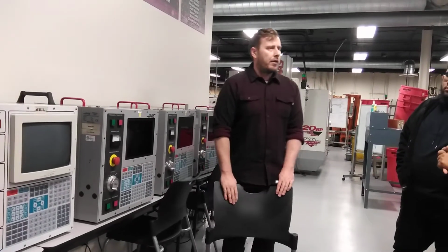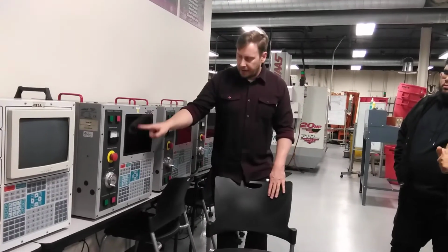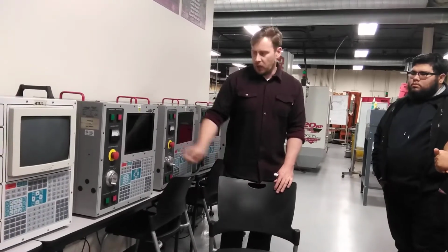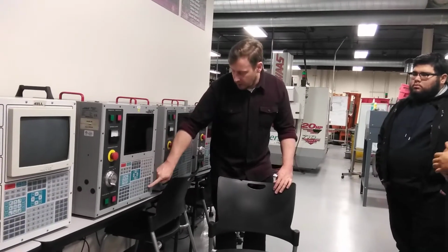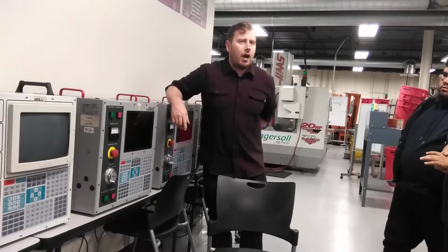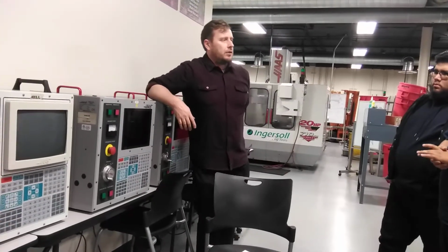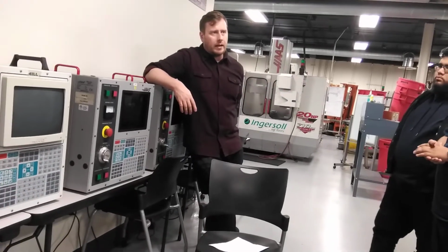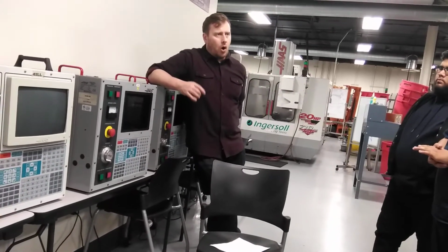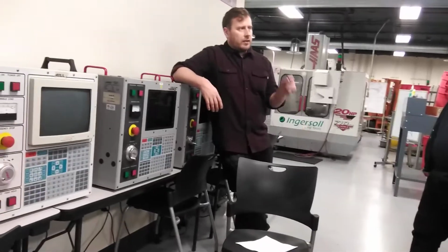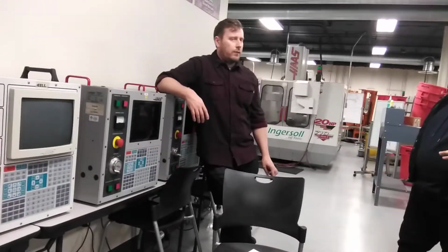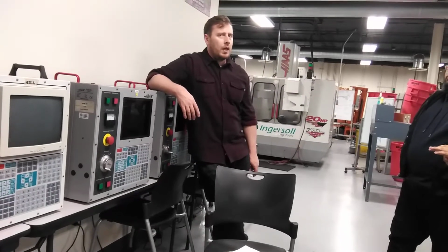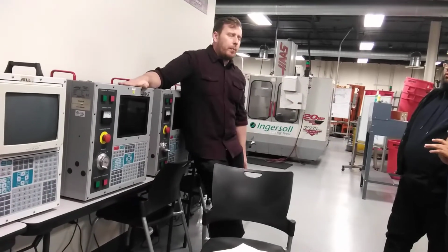Do not forget to put the diameter value. If you put D0, how much is the tool going to compensate? Nothing. You just scratched off your part. So always double check that you set that D value if you need it. Any questions about how to set it up at the machine?